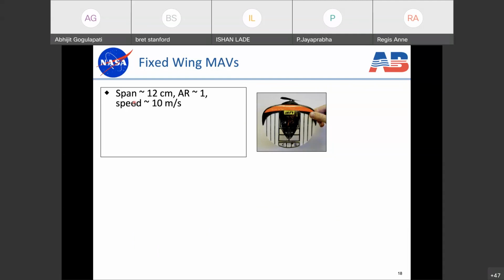And so early on in this research endeavor, we wondered if we could build in passive shape adaptation, some aeroelastic shape adaptation into the wing to try and alleviate these issues. And so the basics of the structure are shown here. This is a top-down view of the aircraft. We have a leading edge here, which is made out of a plain weave carbon fiber, so it's relatively stiff.